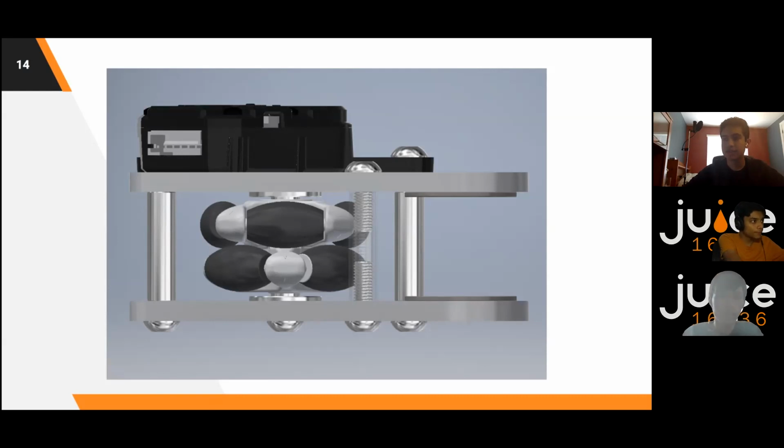Yeah, so PID is a very abstract correction system. It can be used with literally anything that updates its value. So you could use it with a distance sensor, but I would recommend using the odometry modules or motor encoders if you have to. Yeah, and as Sid discussed in the very beginning of the presentation, PID can be used for literally any sensor, like in a coffee machine, for example.